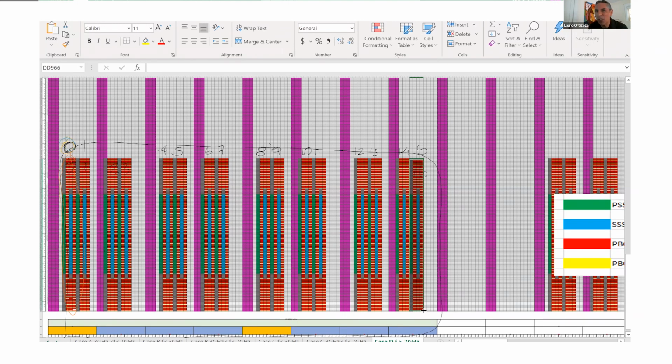You see these yellow lines that run horizontally? These are called demodulation reference signals, right there. Demodulation reference signals are masked with the beam number, right? So that's true for 8 beams. When you have 64, then the MIB carries 3 extra bits that allow the UE to identify the beam number.